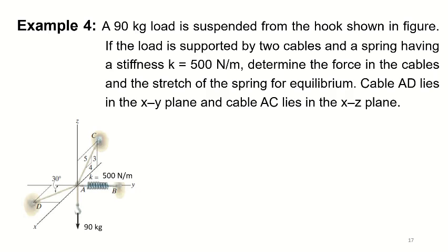Cable AD lies in the XY plane. Cable AC lies in the XZ plane, right? So AD lying in the XY plane means that the force on cable AD can only be resolved into X and Y directions. The component in the Z direction is equal to 0.